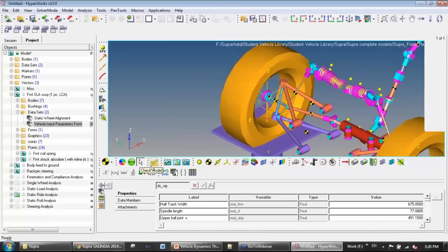Remember, these models are parametric, which means changing things in the data set should be enough for you to move things around in the suspension. Changing things on the left suspension will automatically make the similar change on the right suspension. The template that we have provided is symmetric. You can break the symmetry, however, that involves a few advanced MotionView operations, which you can learn from tutorials.